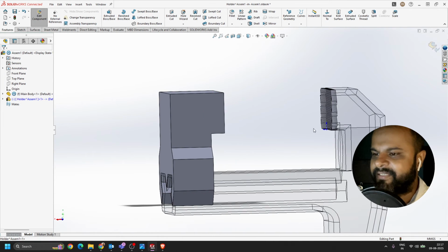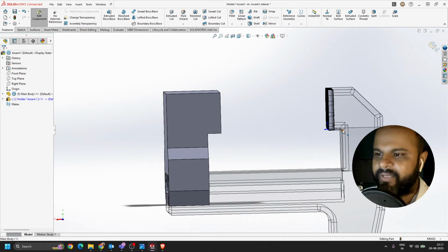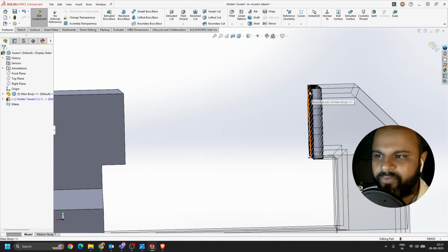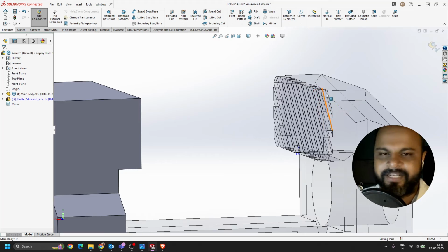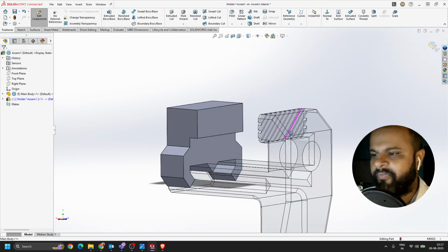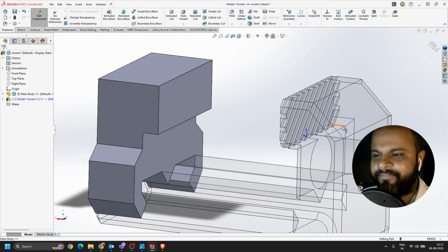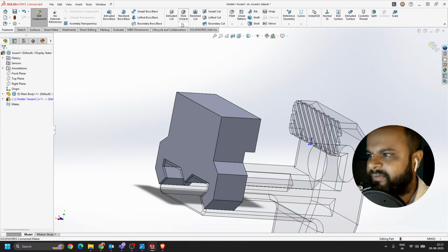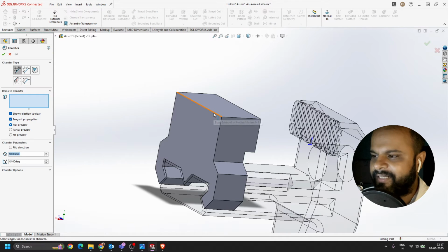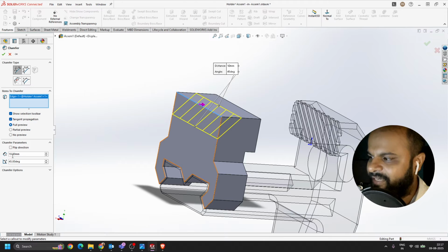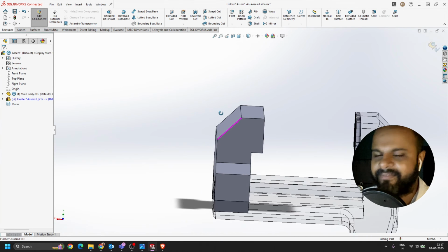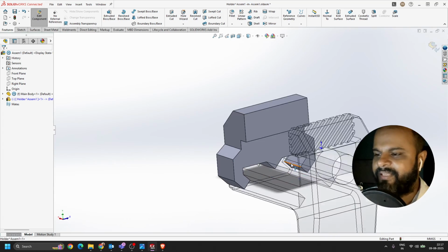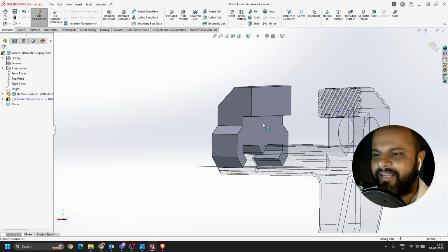If you measure the extended region over here, this is also 5, whereas the 2 millimeter is the depth of these cutouts that we're going to make now. But before that, we'll apply this chamfer that you can see onto this face of 10 millimeter. So we'll go back to our fillet and activate this chamfer. We'll select this corner edge, apply a chamfer of 10, and click on finish. Here you can see like this, right? It's very similar to what you can see right now here.